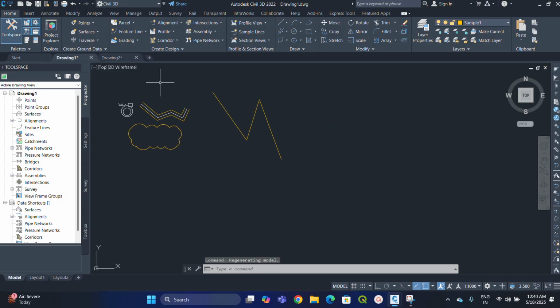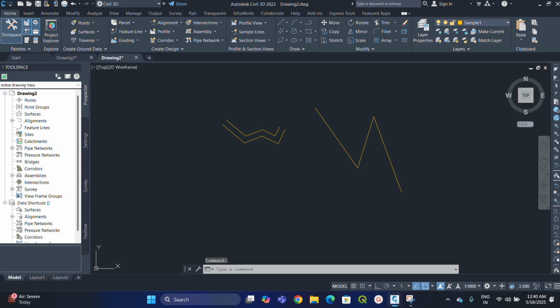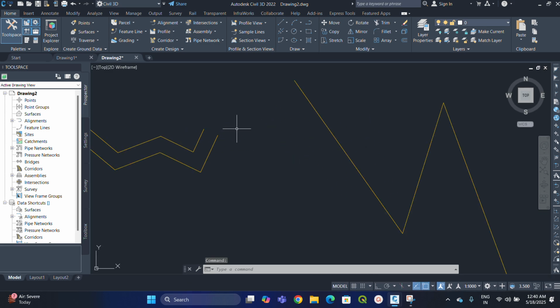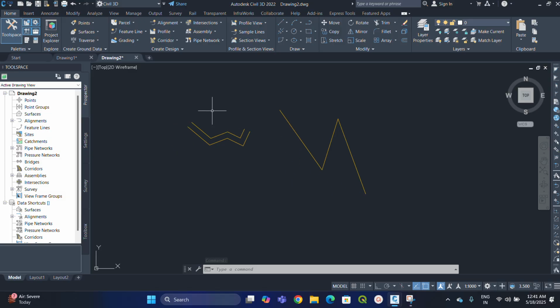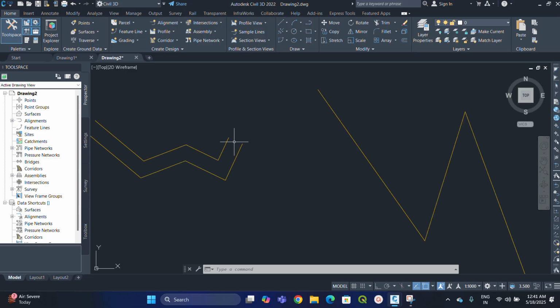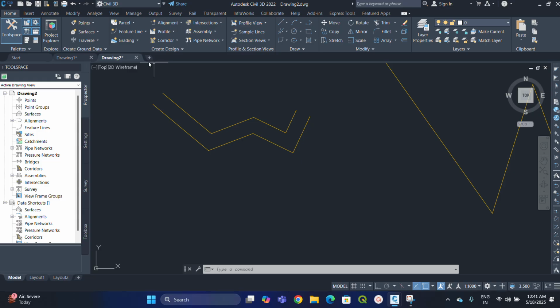As far as utility drawing is concerned, we'll check one more thing as well, like how to xref a drawing. Xref means external reference. While you are working with many drawings, you will need to reference some drawings over the other. So how do you do that? You can give this command called xref, external reference.